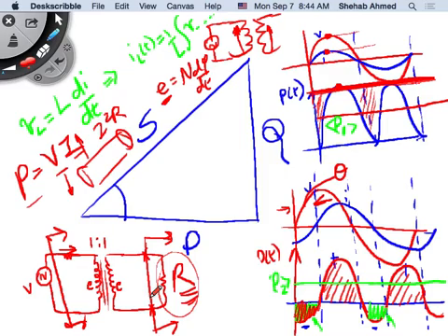You will see a voltage at the terminals of the transformer. At the secondary, you will see it, and at the primary, you will see this back EMF voltage, and the current will not be very high. Why? Because you've set up this magnetic field. This magnetic field will have a value E. This value E will not change if you put a load. It will still be there.